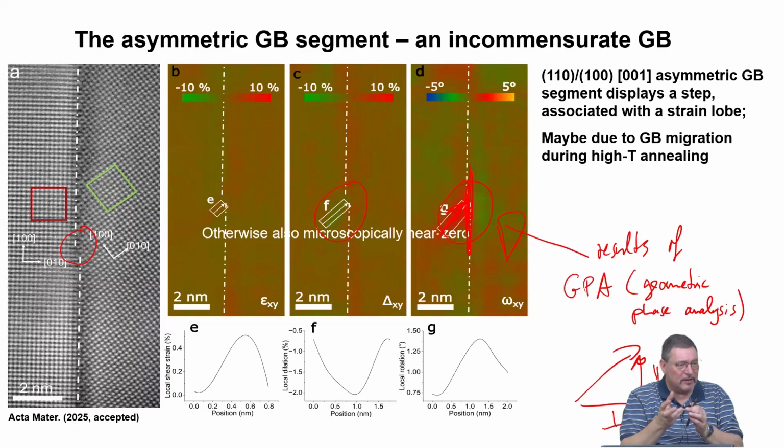You have this stress field, but the stress field of a dislocation is symmetric, right? So you have compressive and tensile regions. If you integrate in a sufficiently large region surrounding the dislocation core, you will again get stress-free. Here we do not have stress-free conditions, so it means that as long as these grain boundary defects are there, we have to treat boundaries and transport along boundaries as acting under an additional force field, which comes from defects of defects, like these steps in grain boundaries.